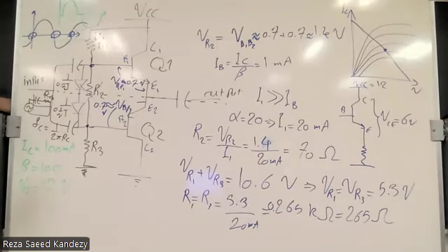Meaning if you have a 10 hertz signal, a very low frequency, your cutoff frequency should be very close to zero. It creates some problem because now you don't have a proper attenuation for the DC, when you have a low frequency signal.